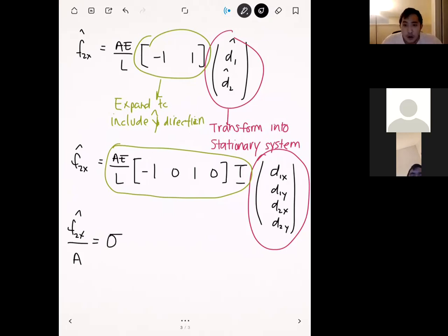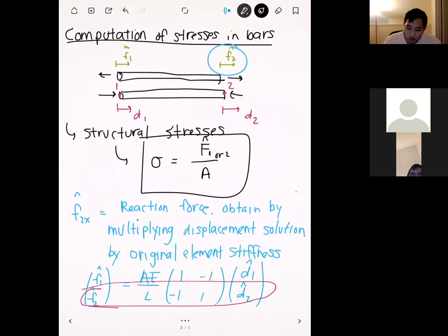Oh, question. So are the y displacements like buckling? Not quite. Buckling is actually quite complicated. You can actually simulate that in ANSYS too. But what I mean by y displacements are just displacements that are transverse to our truss here. A y displacement, at least in the local coordinates, would be a displacement vertically like this, perpendicular to the axis of the element.